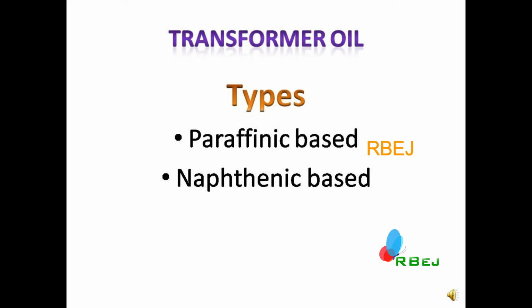Although paraffin-based oil has the above-mentioned disadvantage, still in our country it is generally used because of its easy availability. Another problem with paraffin-based oil is its high pour point due to the wax content, but this does not affect its use due to the warm climate conditions of India.